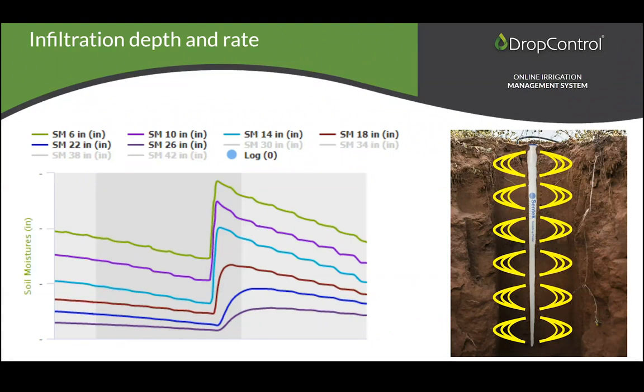As I was saying, I've seen a probe installed with the slurry before. Again, the soil will adapt and compact back together, but in a few weeks or months even. So in the first few irrigation events, you have to be super careful that you're not looking at preferential flow in that slurry. The way to confirm that is basically going out in the field and watching it. We had a probe telling us, based on the irrigation, that the water was getting all the way down to 4 feet, but we went out there, augured, and the water was only getting down to 2 feet. That was happening because the structure of that slurry was letting water by faster.